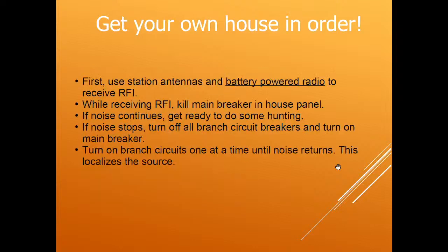So the first thing you want to do is get your own house in order. Basically the way you do this is to arrange to be able to listen to the RFI with some kind of battery-powered radio. Whether you can run your station transceiver off of a car battery, a lot of people have it set up that way anyway for emergency backup, or if you have another kind of radio that's battery powered, set that up to listen to the RFI and then kill the main breaker in your house.